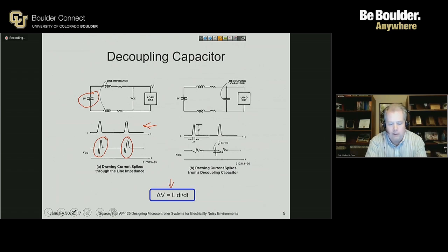In this particular case, we see these graphically pretty large delta V's superimposed on our VCC rail, and we can imagine, hey, wait a second, that looks significant. It's very possible that I'm getting a voltage drop because of that current spike that's causing VCC to go down below the minimum value of VCC temporarily.